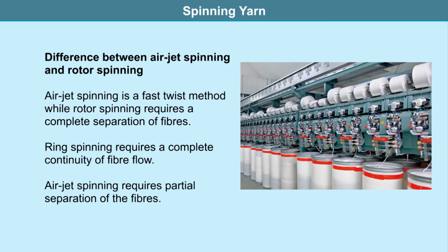In the fiber strand, the twisted core will immediately tend to untwist and the detached fibers will wrap around the core fibers. These result in a yarn consisting of a core of parallel fibers wrapped at some points along its length with fiber wrappers. The primary source of strength of air jet spun yarns results from effective fiber wrapping.